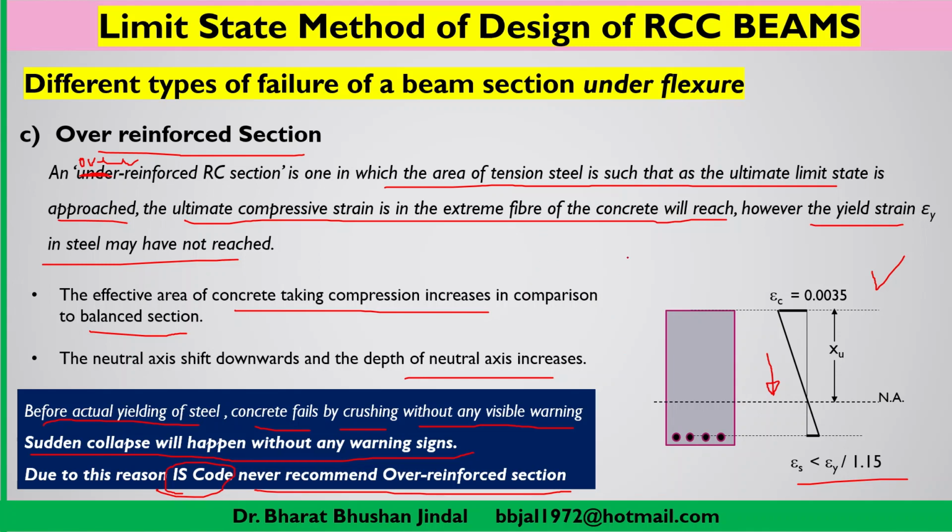So here the third question is why the code suggests, or why we suggest, that whenever an RCC section is designed, it should be designed as an under reinforced section. However, the balance section is more economical in comparison to under reinforced. So the very first question is why an under reinforced section is preferred and why a balance section is not preferred, even though the balance section is more economical, and as I have already told, an over reinforced section is never recommended. So you can compare, based on whatever you have learned, and you can refer to other sources of information, just like some standard books. Various good books are available even in PDF format, and go through the IS 456 guidelines.